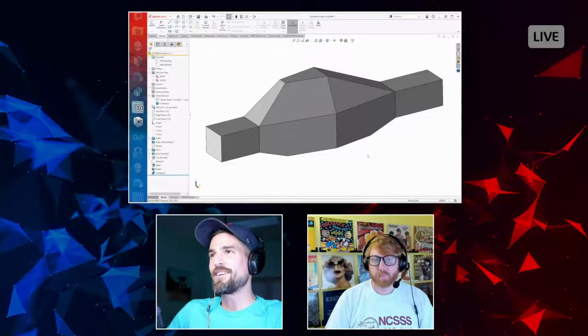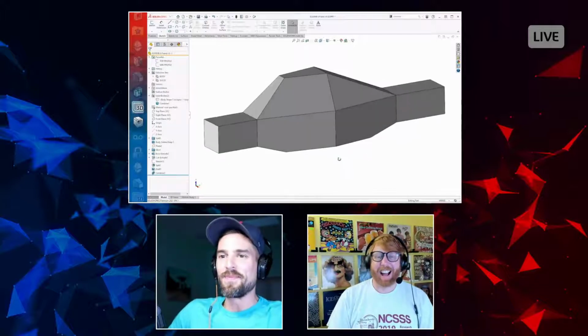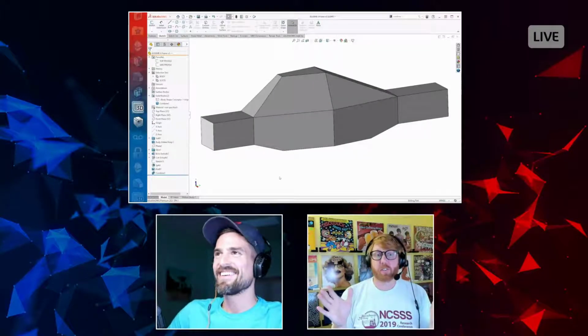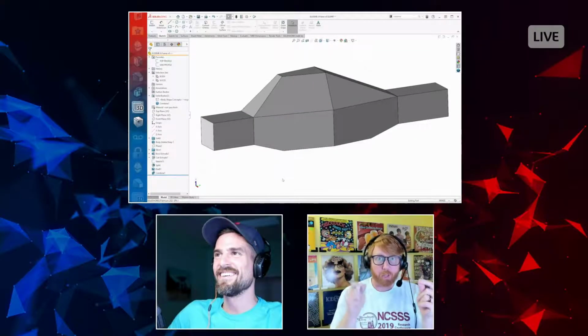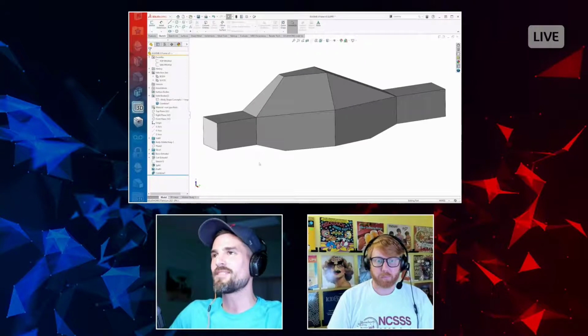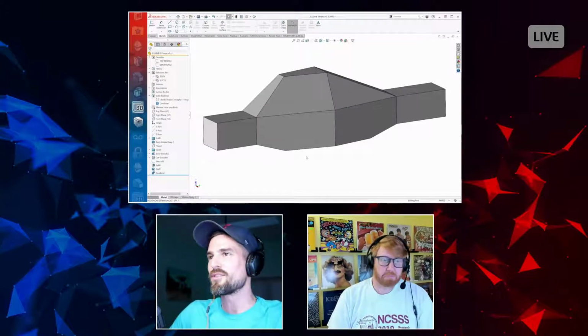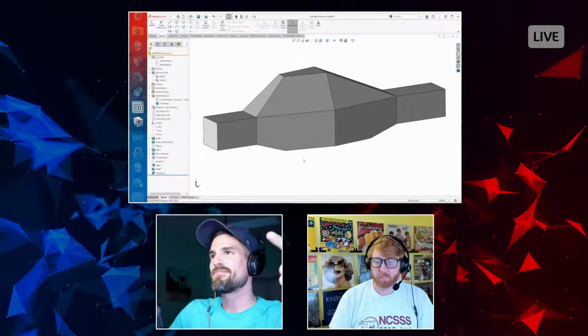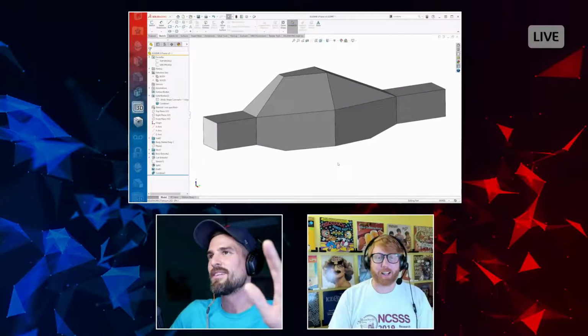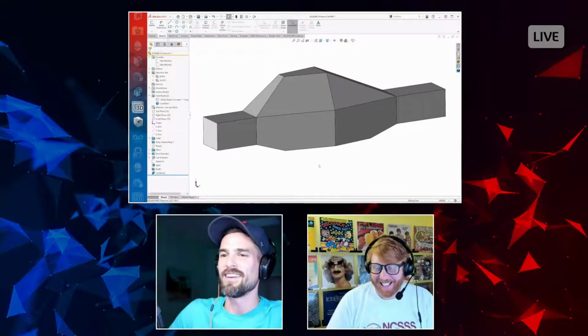Either way, we gave it a huge endorsement. But seriously, the only time I use 3D splines is when I'm going from one point to another point, so that's a 2-point spline. I'm probably not going to use a style spline. So how hard was it for me to create this geometry? A couple of extrude cuts, separate the bodies and draft it. I arguably could have drafted without separating the bodies. We'll get to that in a little bit.